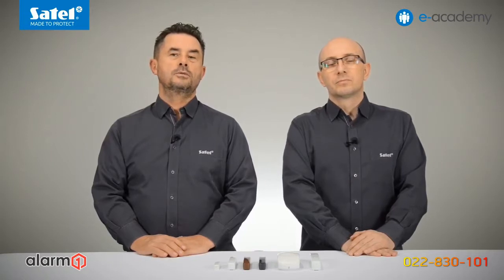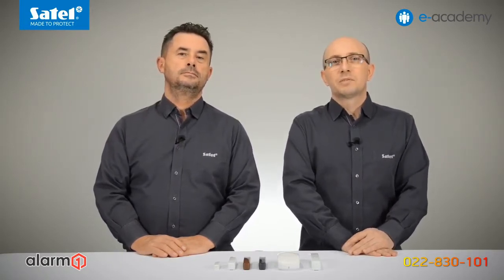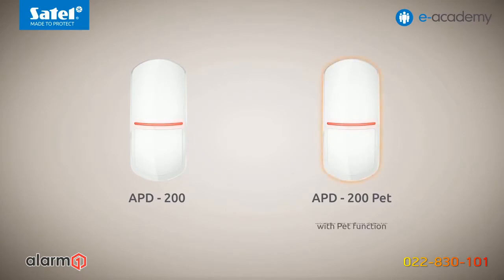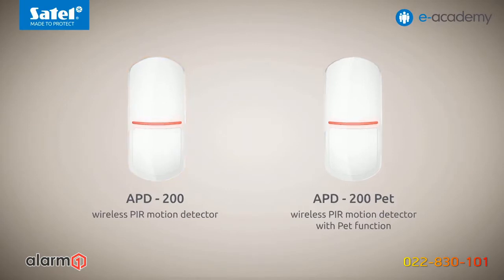In addition to controllers, the ABAX 2 wireless two-way system includes a number of devices of various types. Now let's take a look at each of them briefly. The first two are APD200 and APD200 PET wireless passive infrared detectors. They differ in that the APD200 PET detector has the function of pet movement immunity. On the other hand, creep zone control can be enabled in the APD200 detector.